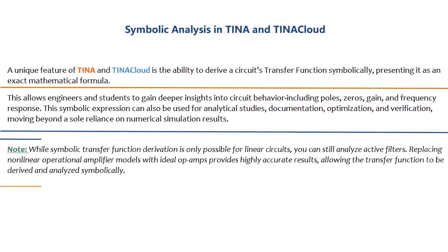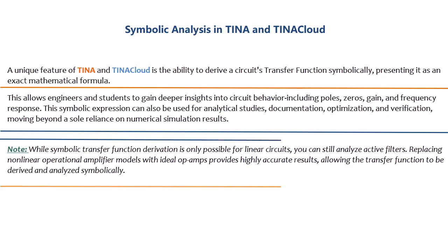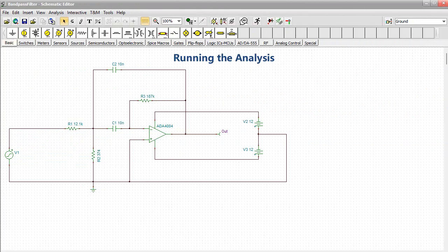Note: while symbolic transfer function derivation is only possible for linear circuits, you can still analyze active filters. Replacing nonlinear operational amplifier models with ideal op-amps provides highly accurate results, allowing the transfer function to be derived and analyzed symbolically. Running the analysis.